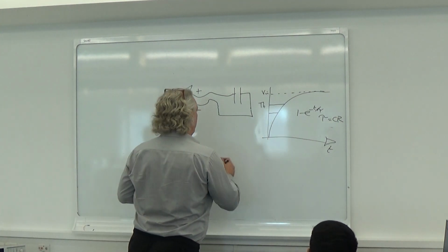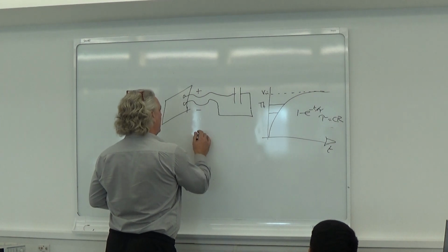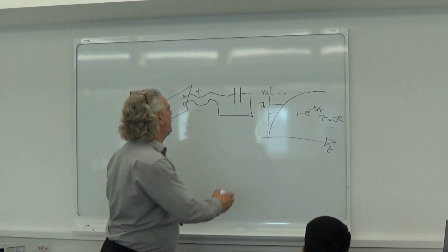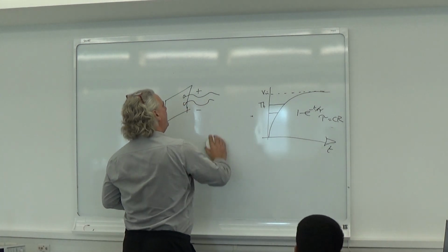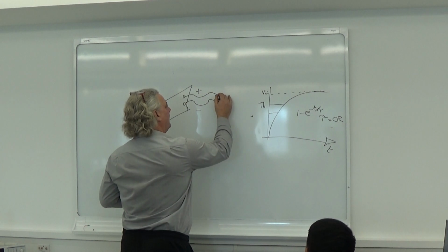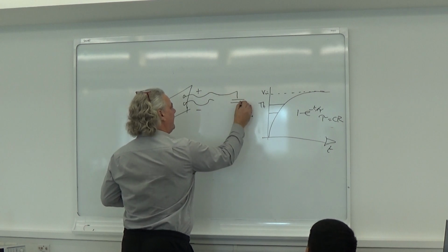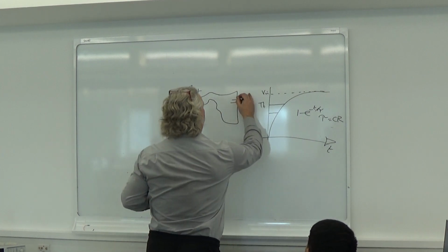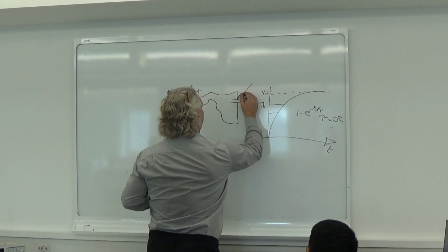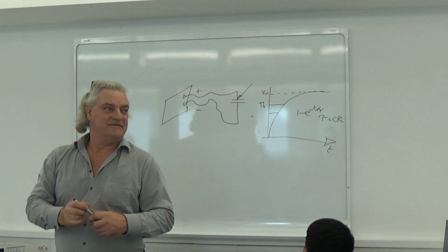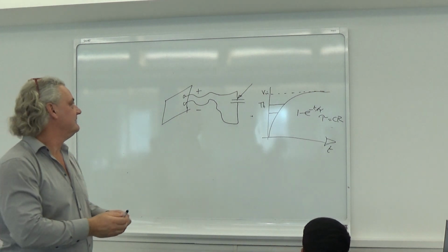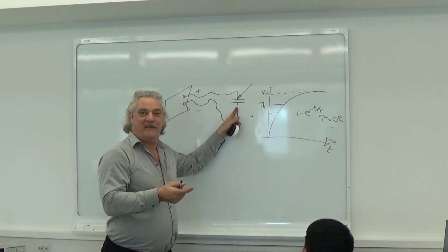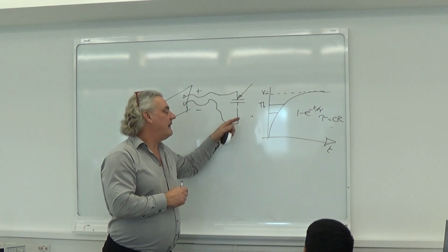So let's draw this in a slightly different way now. Turn the capacitor through 90 degrees. And now a more realistic diagram of what we have is this. So we're going into a capacitor like this, and we know this point here, the top of the capacitor. What's the bottom of the capacitor then? What's the voltage here? Well, that's a difficult one to answer actually, but for all intents and purposes, you can imagine that's ground that side.